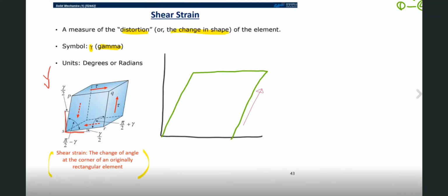So first, I'd like to draw here tau, and according to the equality of the shear stress, we can draw another shear component on the top surface of this pure shear deformation element as tau, and the parallelly located faces have the same magnitude and opposite direction, another tau, and adjacent faces with reference to its original face, the direction away from its intersection, right?